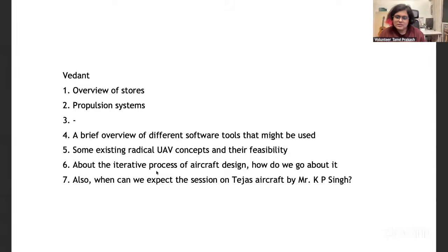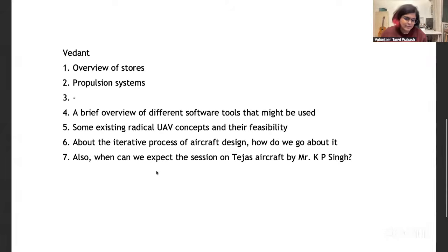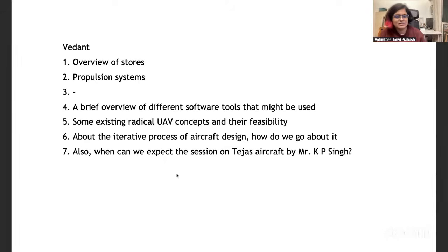There are 2 or 3 tools that are available and easy to use in the aircraft design conceptual stage. There is OpenVSP, in which you can quickly make 3D CAD for an aircraft and do some aerodynamic estimation on those. Then there is a software called XFLR5, which some of the teams have also used for solving the DCE question paper. So primarily these 2 are quite easy. I'll repeat the names and in fact I'll also put them in the chat box after this. It's